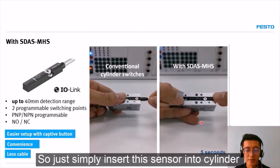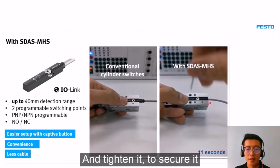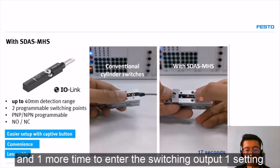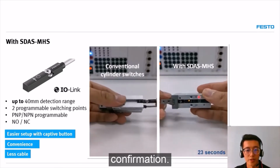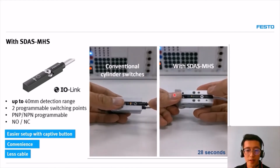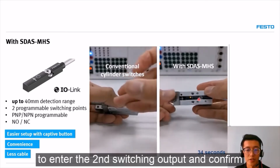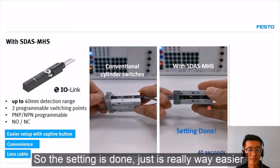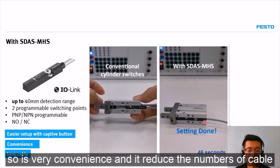Just simply insert this sensor into the cylinder and tighten it to secure it. Touch the capacitive button here 3 times to enter the menu, and one more time to enter the switching output 1 setting, and one more touch is for confirmation. Now I extend the cylinder and set the second switching output: enter the menu again, select type 2 to enter the second switching output, and confirm. So the setting is done. It's really way easier compared with conventional cylinder switches. It's very convenient and it reduces the number of cables.